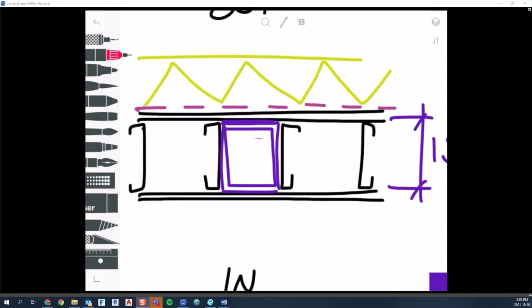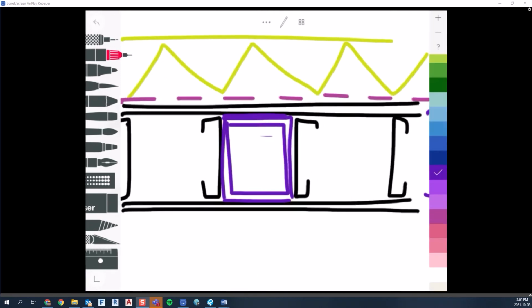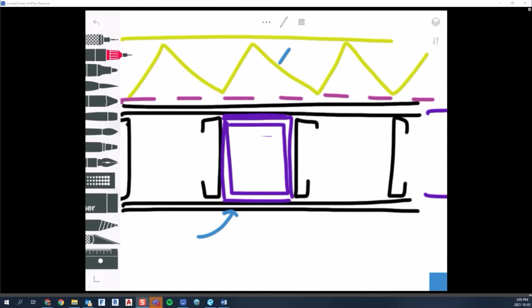So the problem with this approach is getting that gypsum board past that column without it being visible, basically. So the taller you get in the building, the more out of plumb maybe that piece of steel will be. And all of a sudden, because there's zero tolerance there, it's very hard to get that gypsum board past that column sometimes. And same goes for the sheathing. So as the buildings got taller, we started saying, well, yeah, that's becoming a problem. Buildings move a little bit, and you'll see some bumps in the drywall and stuff like that.